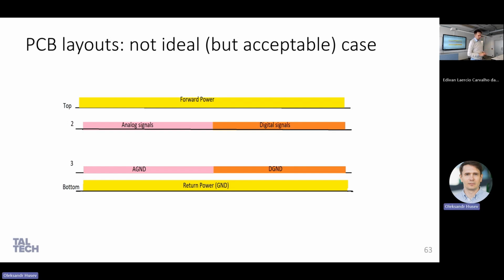When you said distribute capacitors, I was thinking what could be the value and how one can estimate it. Well, it's defined in a simple, but not very simple way. Somehow you can estimate these parasitic inductances. During the switches, you need to know how much energy you can accumulate here, so your energy will be redirected to this capacitor. And if the energy capacity of this capacitance is larger than this, it means that you will have enough capacitance in order to avoid any spark.